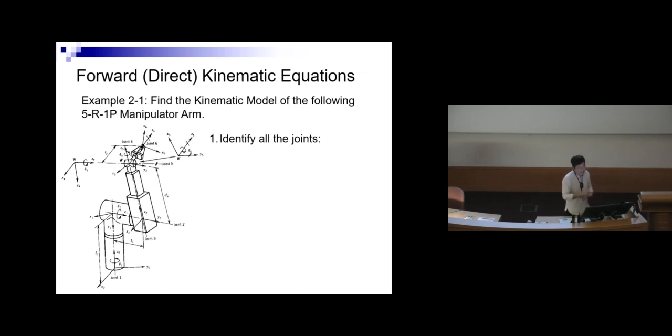Okay, so we take an example. This is a more complicated example than earlier on, but this example is closer to what you have for your assignment for the UR5e. So bear in mind that when you do the kinematic equations, when you do the kinematic modeling, you should have the robot start at the 0 position. So you have the robot at the 0 position.